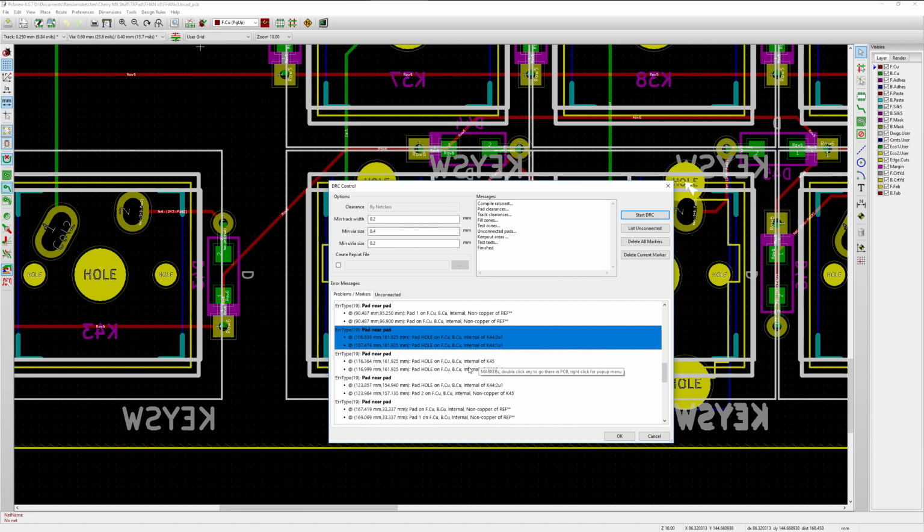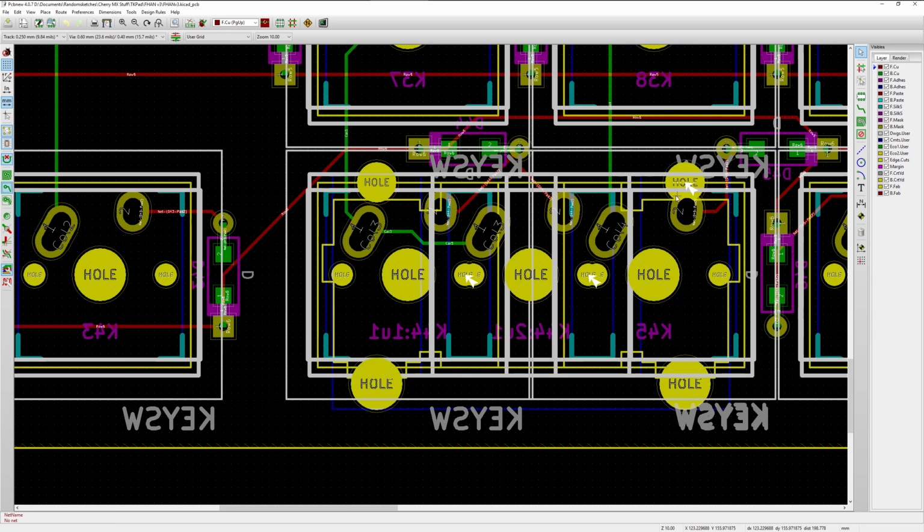Then we've got a hole and half a pad. Now, this is of course for the stabilizer, and the pin will go through here. I don't think it's too much of an issue. Had I had this flipped around the other way, then the bigger hole would have been there, or the switch footprint would have been down here. But then you're going to get a little bit of a weird orientation for that switch position. I'm okay with that. Half a hole, that's not a big deal because there's still plenty of contact surface there for the pin to be soldered to. It's not a critical error.